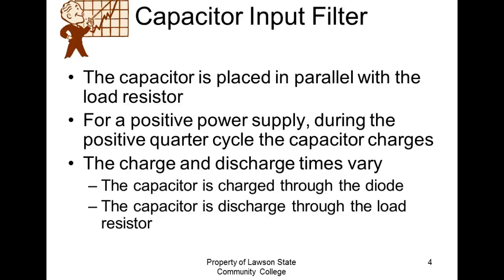So if you make your negative common and use your positive for your hot leg, then it'll be a positive power supply, but you just as well could have made what? The positive common, and then you'd have a negative power supply. So that's why when you see an integrated bridge, it doesn't label common, it just says what? AC. Two leads are labeled AC, and then one lead's labeled plus, and the other one's labeled minus.